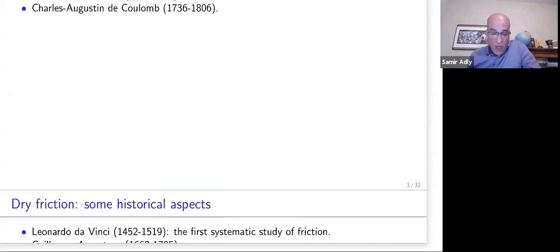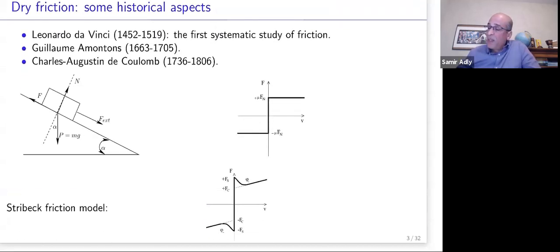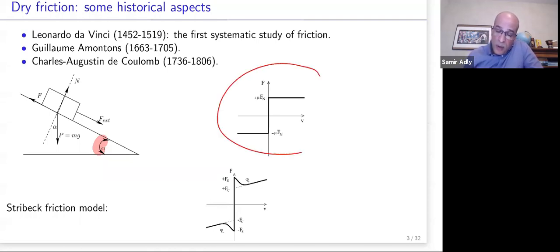The laws here can be illustrated by this classical example of a brick resting on an inclined plane, in equilibrium and motionless. The force of gravity is opposed by static friction, and as the angle of tilt of the plane is increased, the brick will eventually start to move downwards as gravity overcomes the friction resistance. A simplification of the Coulomb dry friction that we will use here is given by the set-valued map.